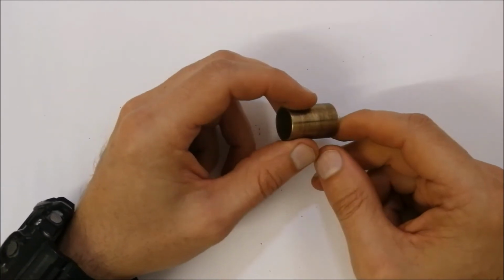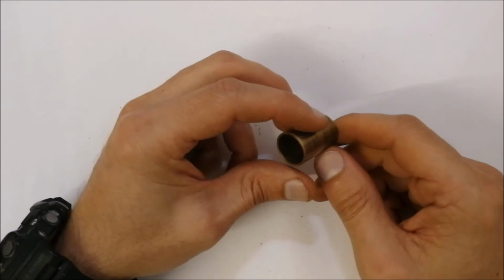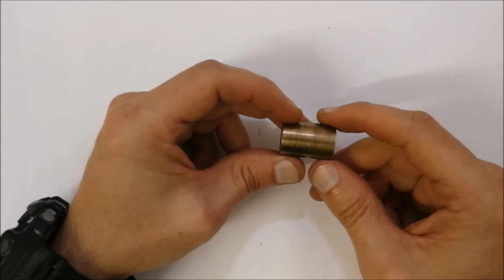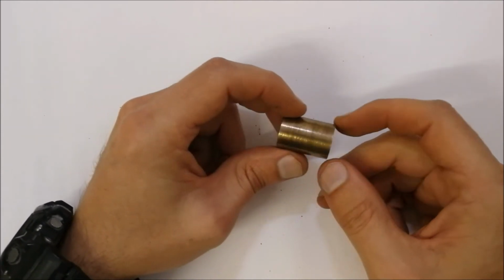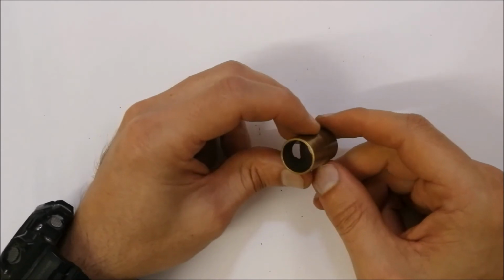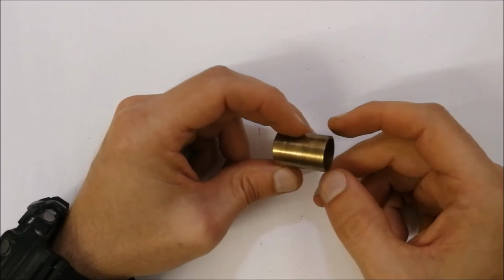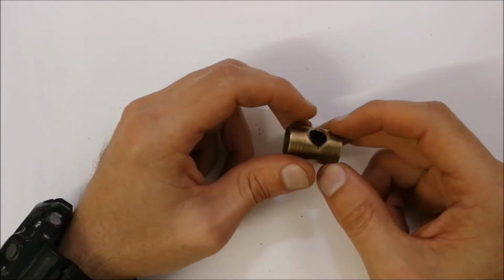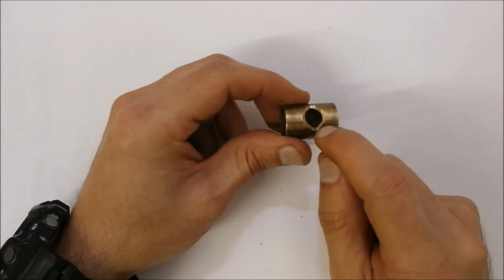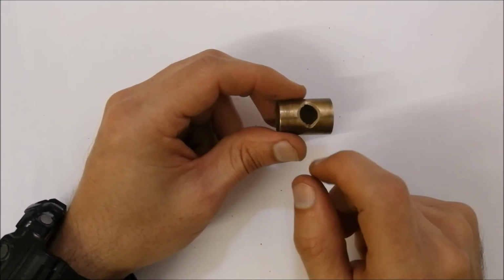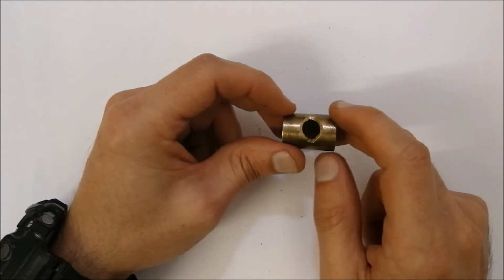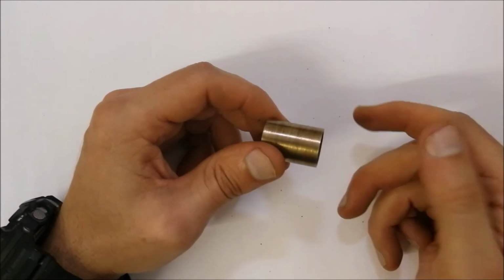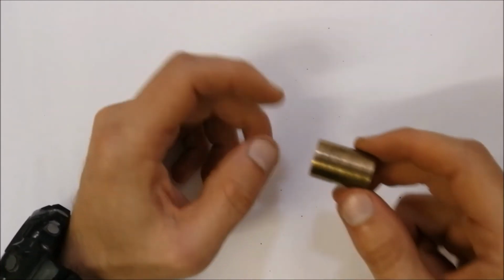And Teflon has a property that it is self-lubricating. So if there are not too many harsh forces acting on these bushes, you can have the bushes made out of Teflon, and you don't actually need to worry about lubricating it with these grease holes, because of the self-lubricating properties that it has.